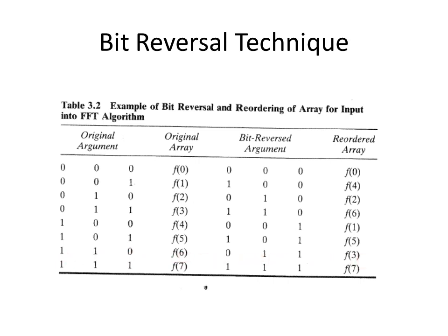If we arrange the input in ascending order, then we will not get the output in the same order, but the output is arranged in a particular manner according to this bit reversal technique. So for our ease, we usually arrange the input in this pattern, which is the reversed pattern. So at the output we will get the frequency domain contents in ascending order. We will see it in a later slide also.